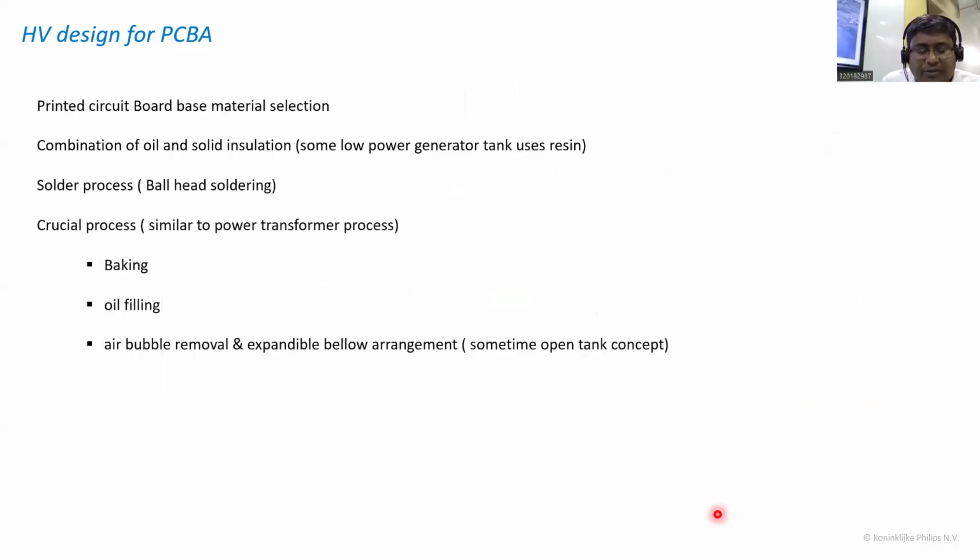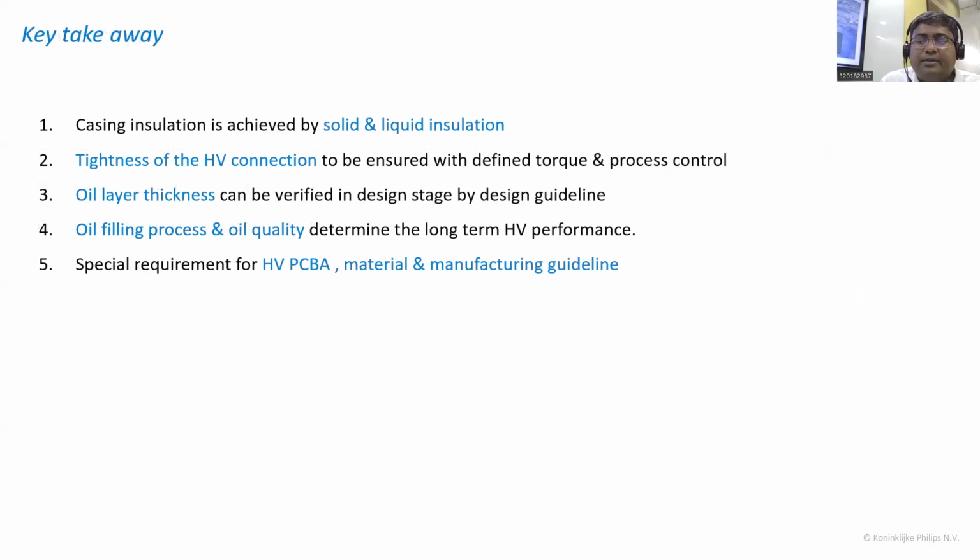So as all high voltage people know, it's not only the design, the process plays a major role in really obtaining the high voltage. Yeah, I think we still have 15 to 20 minutes. On the DC high voltage design, not only the design, the processes are equally important. So there is baking to demoisturize, oil filling, air bubble removal, and all these things need to be taken care of. Only then does the power supply part of the X-ray device reach a level where it functions satisfactorily.